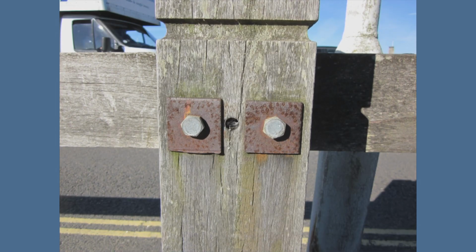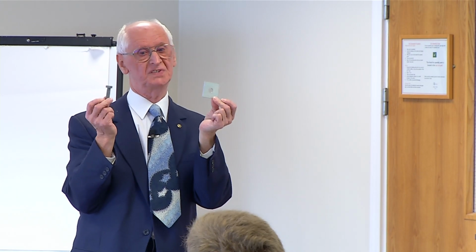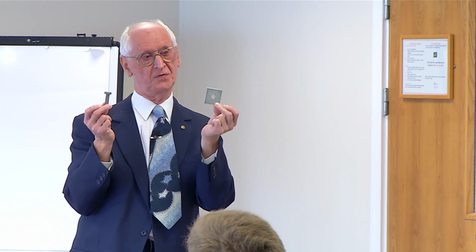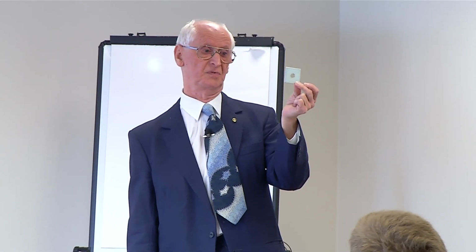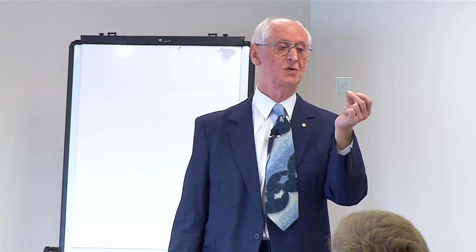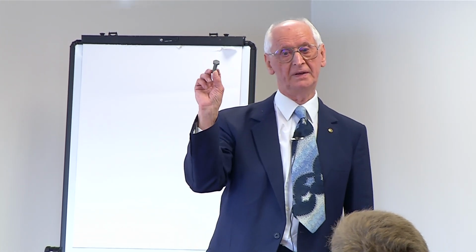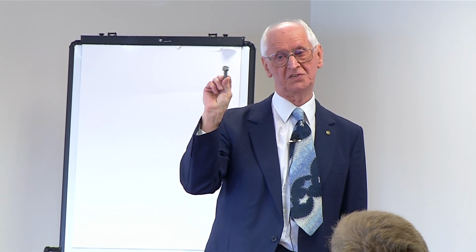But here we have a situation where the bolt here, this is hot dip spun galvanized. The washer, this one, bright zinc plated. Now they are both protected with zinc, but there is a vast difference. This one, outside, 2 years life before you get down to the base steel. In a marine environment, probably 12 months life. This one, 30 years plus in an outside environment. And there's a vast difference.